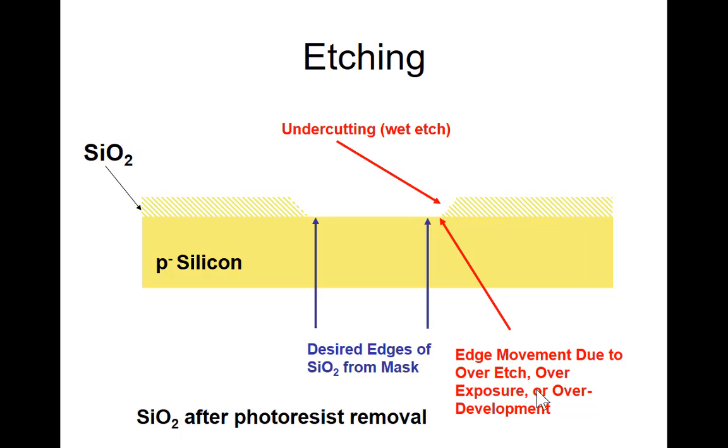And so afterward, after you remove the photoresist material, the shape that you have is about 45 degrees at the end. Well, this again is an ideal drawing. The actual shape here may not be a straight line like this. It is more going to be curved.